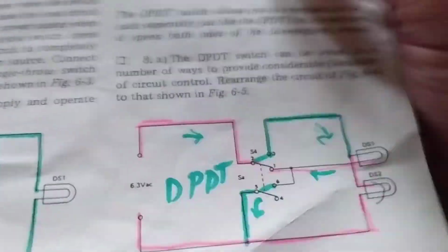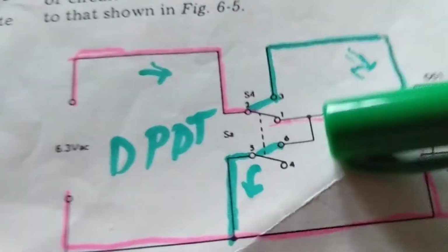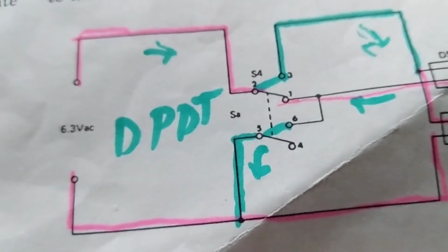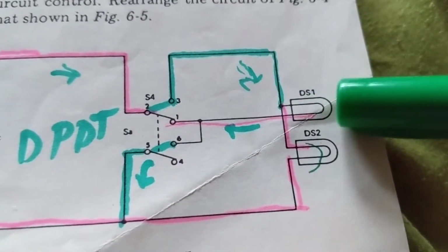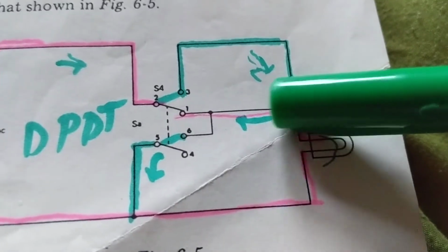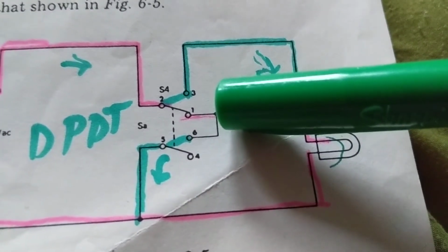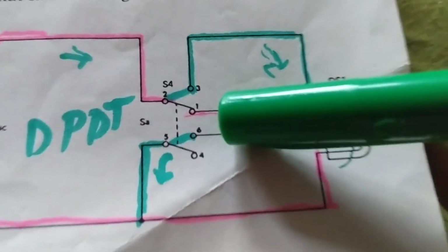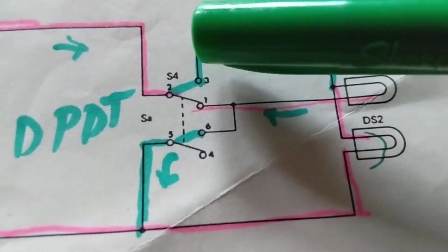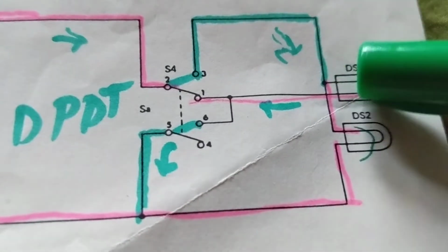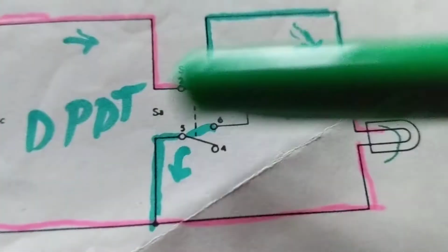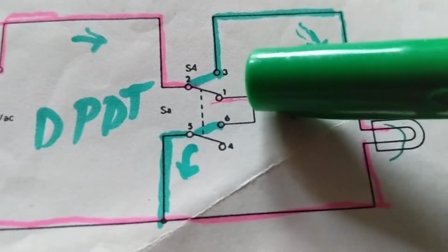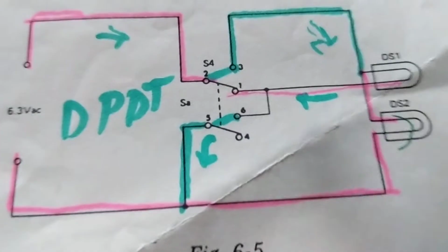Let's take a difficult one. Again, we're ganged together. When I flip this part of it, I flip this part of it. Come over here, we come over here. Go in here. We come into this switch. We go out the switch. Right? We're in the upper position. Upper position means 2 is connected to 3. We went in, current flowed, comes out. Where does it go now? 6 is connected to 3 because it's in a rest position. We go here, and back to the supply.